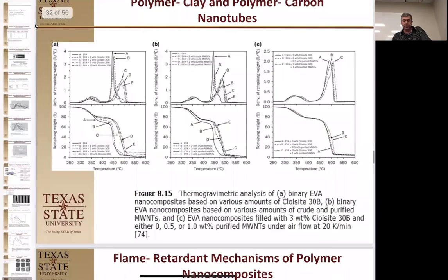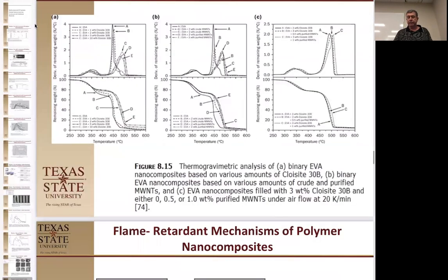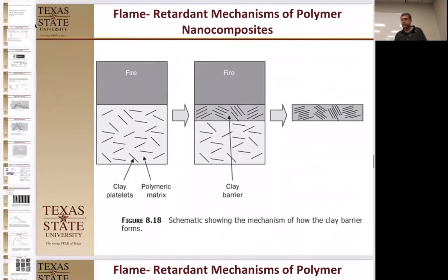So they did some other heat studies here, looking at the binary mixture, and they're drawing some conclusions that the heat release or the weight loss of mass is changing here. I don't see a significant difference in any of these, but the heat release rate was a significant change. That was definitely tangible. And again, I don't think you can avoid a heat release rate or cone calorimetry experiment by trying to use TGA. I don't think it is an appropriate supplement.